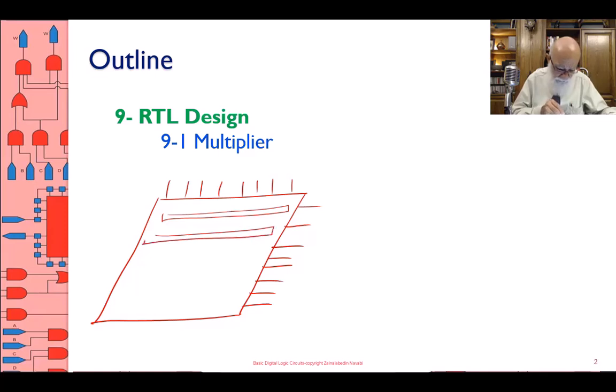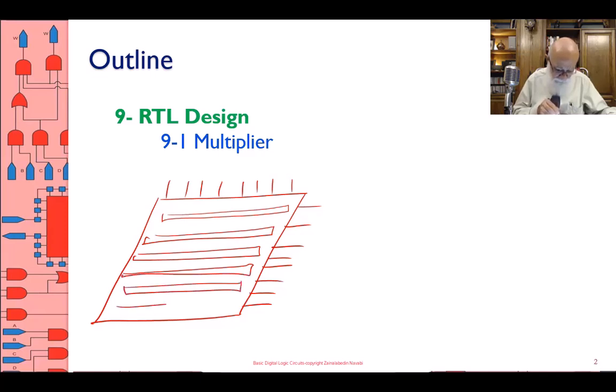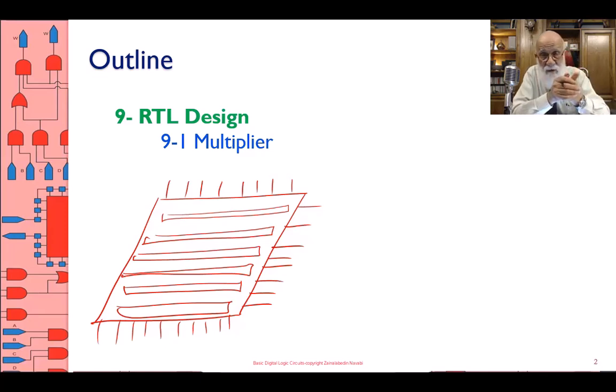So it has 8-bit adders that are being used to add the data that come in from the top. What I'm saying is it's an 8-bit multiplier producing 16-bit results, and the 16-bit results will be formed by these adders that are there.